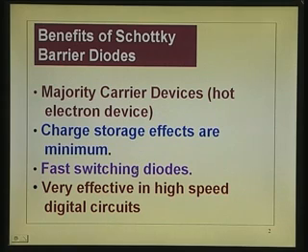See, the switching speed of a diode is lower if there are stored charges. When there are stored charges, it behaves more like a huge capacitor, a lot of charge is stored. Then to turn off the device, you must remove the charge completely. So, that takes time. From the on state to the off state, the charges will have to be removed. So, delay times are involved. That is why p-n junction diodes are slower, because of charge storage effects.